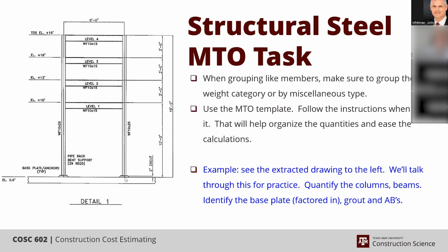would be, because normally your grout needs to fill up the base plate and then angle at a 90 degree or a 45 degree angle from the edge of the base plate. In some cases, I've seen it where they require you to go an inch past the base plate and then do your 45. Very rare, but I've seen it a couple of times.